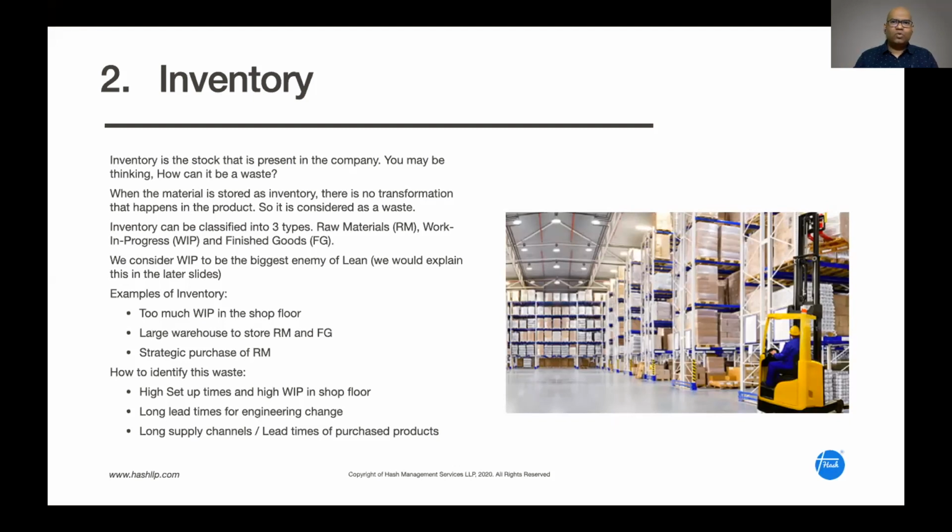There is one more reason which will increase inventory, and that is high setup times. Many times people don't understand the correlation between setup time and inventory. If the setup time is high, the changeover is high. Let us say it takes 5 hours or 8 hours for a changeover. What people do is try to avoid the changeover. They don't want to do the changeover frequently. So I run this particular setting for 1 week. I produce more of the same product and keep it, because my setup time is high and I don't want to do frequent changeovers. Because setup times are high, I will also produce a lot of inventory, work in progress, and store it. So setup time also has a correlation with high WIP.